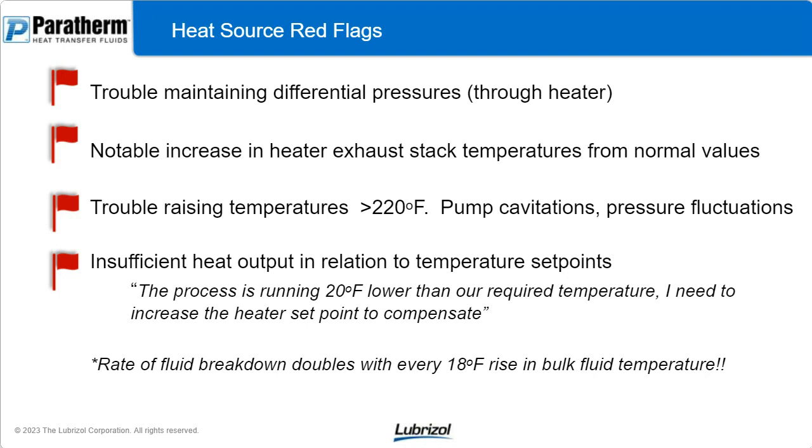One really good red flag, a quick everyday or weekly check, is to just take note of the exhaust stack temperature, the waste heat stack coming off of the heater. That's waste heat. That heat that's leaving the top of the heater is heat that did not go into the fluid. There's a regular everyday range of temperature that should fall within normal values.